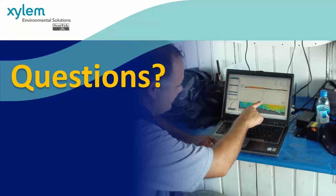And then also to highlight some of the reasons why you might want to do that, there's new features in RSQ to post-process data that were not available in River Surveyor Live. For instance, you can subsection the transect, so you can chop out from a certain sample number to a certain sample number and have that as a separate discharge file, or for whatever reason you might want to subsection a data set. We have a few other things in there that are helpful.